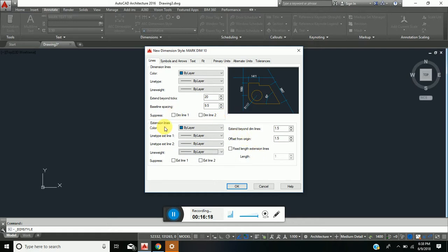Now, still referring to your extension lines, you would want your extension lines to protrude beyond your dimension lines. You wouldn't want your extension lines to just stop sharp at your dimension lines. You would want them protruding a little bit, and 2 mm is usually a reasonable amount. 2 mm times the scale, however, would have given us 20 mm.